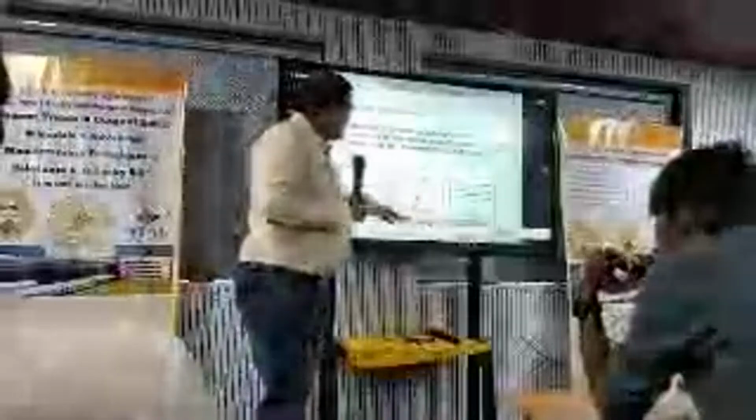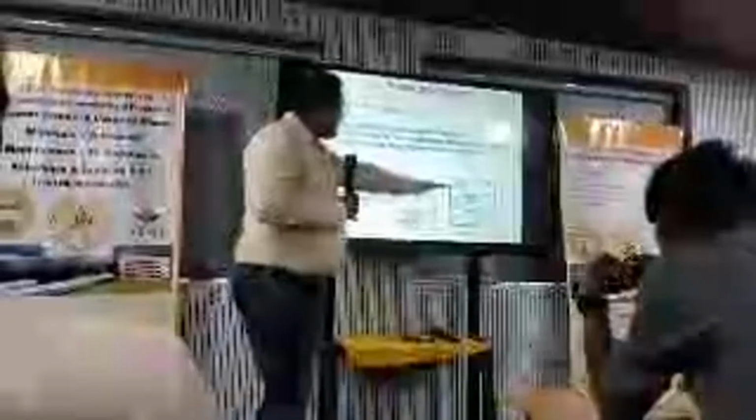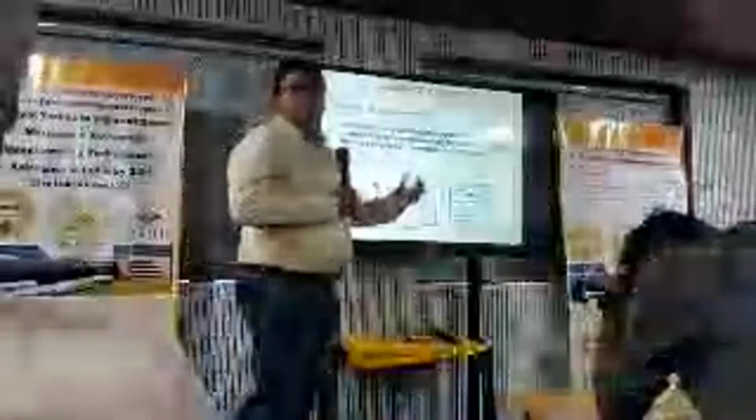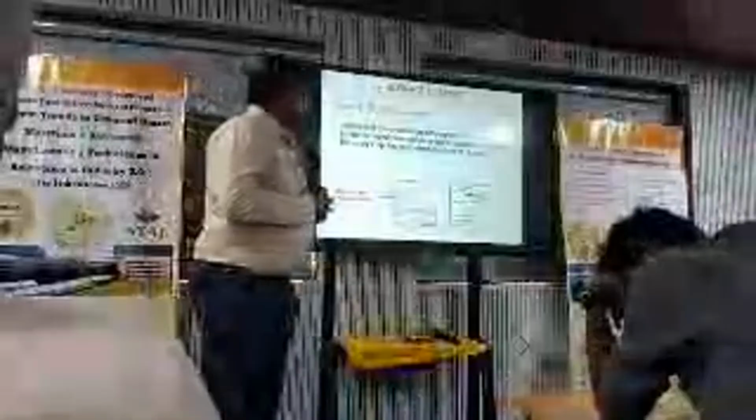So what we are doing, we are increasing the damping of the structure, whether it is CLD or FLD, in both cases we are increasing damping. If you increase the damping, what will happen? More rapid decay of unbalanced vibrations. So very quickly the vibration energy will be converted or reduced. And also faster decay of freely propagating structure borne waves.